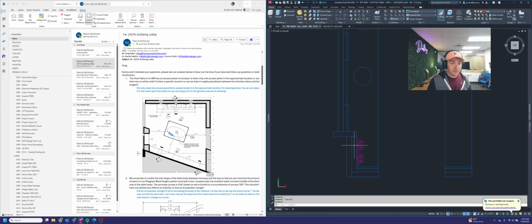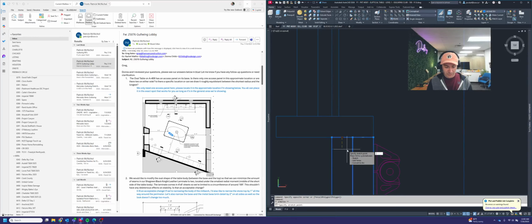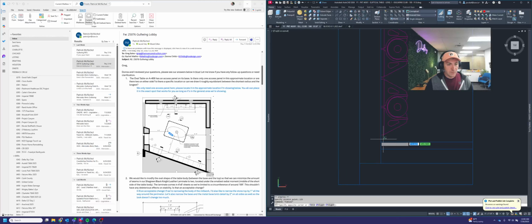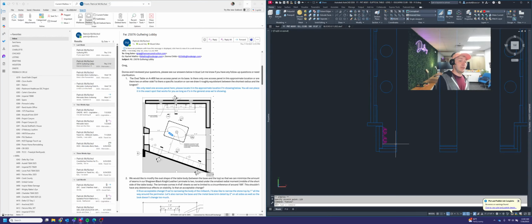I would definitely recommend, to make things easier to be removable, that we probably want to lower this down 1/8 of an inch. And I think I'm also going to do the same thing for this here. I'm going to raise that up 1/8 of an inch in this guy as well. What I'm doing that for is to give it some play or wiggle room, so when you go to attach or remove this, there's going to be the ability to pry this off, and it shouldn't be too hard to do. So we're going to use that for now.